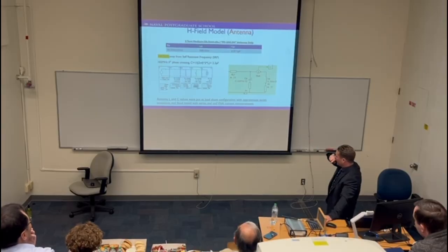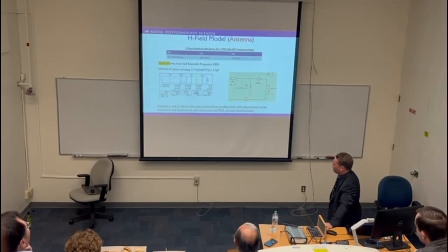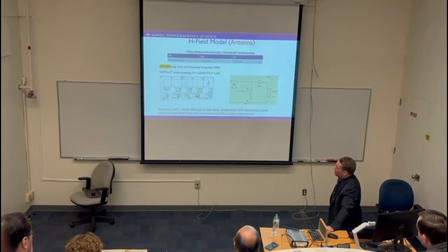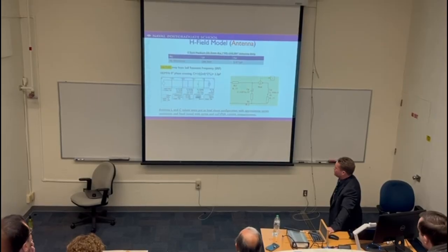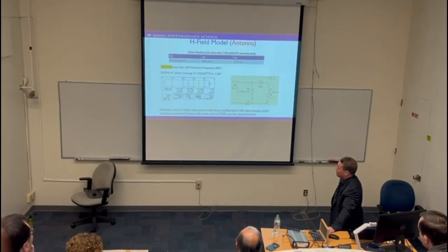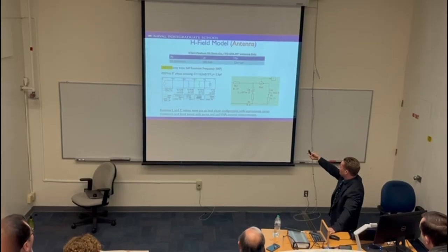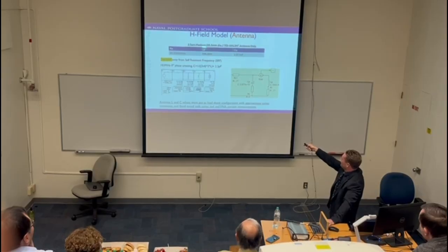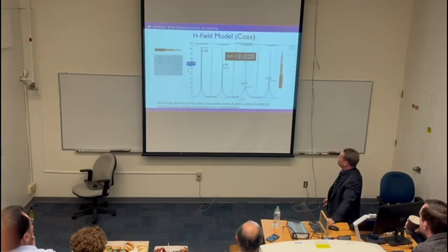So again, I took this from the Smith chart. I just looked at essentially far enough away from the self-resonant frequency. I got an accurate inductance looking at the Smith chart. Where it crossed the 0 degree mark is essentially where it's going from inductive to capacitive, and I was able to calculate the capacitance from that, from the 1/√LC relationship, and plug these values in. You can see here that the values that are here are basically plugged in here and match all these. So everything was lining up. So now I knew what my antenna was going to be.